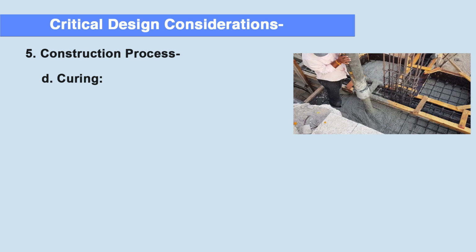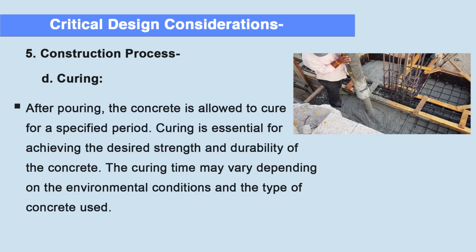Then the next step is curing. After pouring, the concrete is allowed to cure for a specified period. Curing is essential for achieving the desired strength and durability of the concrete. The curing time may vary depending on the environmental conditions and the type of concrete used.